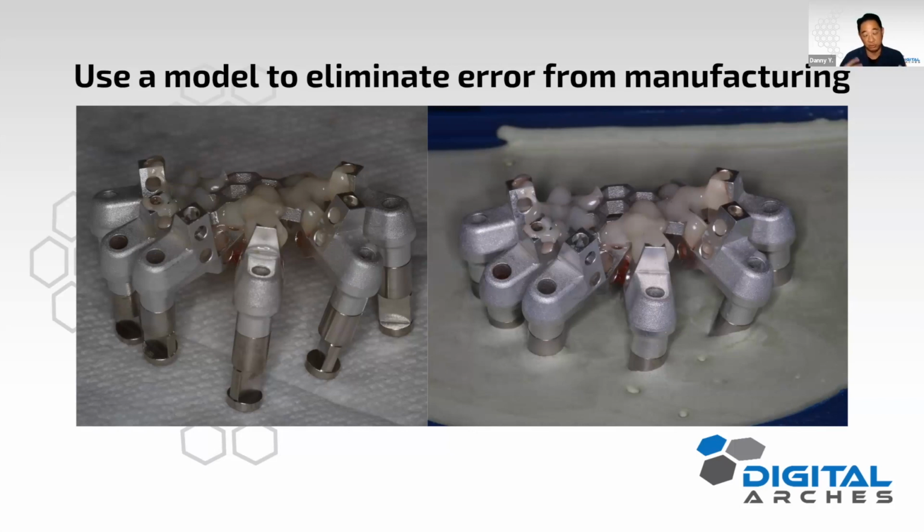When you start to combine third-party printers, third-party curing units, and third-party washing stations, and this is something we learned ourselves, you're going to add more error to that process. And I had one lab tell me that when they were testing everything on the model, they actually found that error happens more often than not, enough that things don't fit the model after it's printed or after it's characterized, because as you're characterizing, you're curing too.